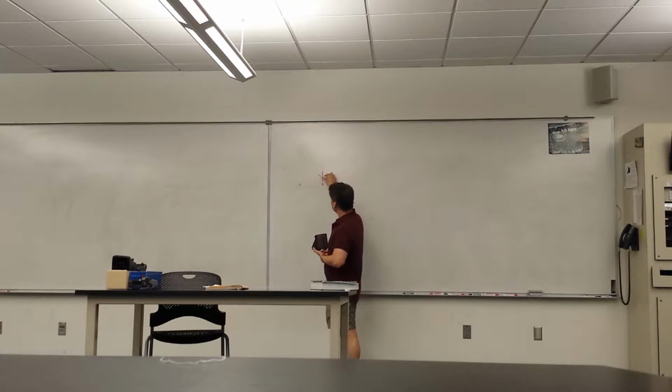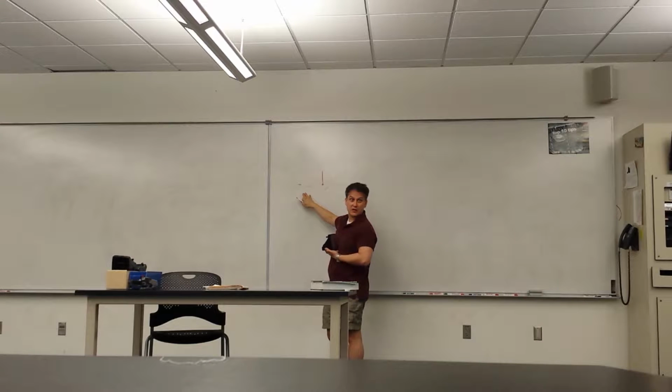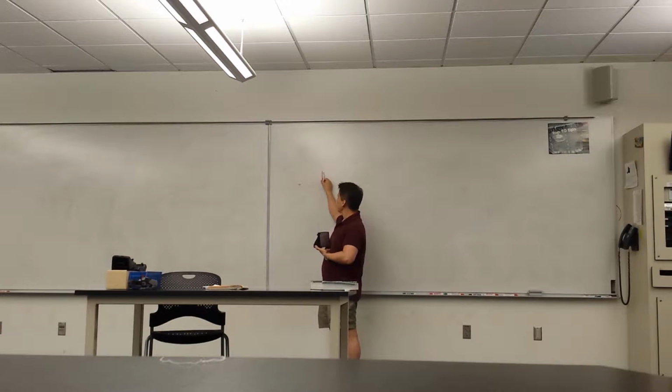The net result is that it will deflect left or right via the magnetic interaction between the current and this magnetic needle. The deflection is proportional to the amount of current that flows. Not only that, but if current flows in the opposite direction, the needle deflection will go opposite.